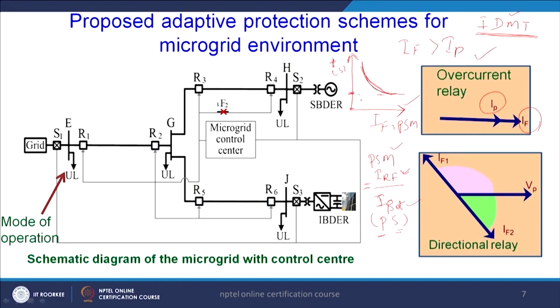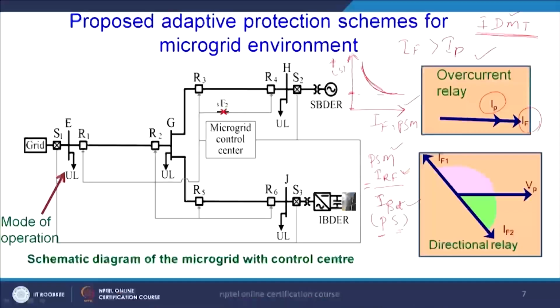We also have very inverse characteristics based overcurrent relaying principles, or extremely inverse type of overcurrent relaying principles, but in general in industry we prefer the IDMT type. After that, the time of operation is calculated and we maintain the TMS, the time multiplier setting, which sets the time of operation of the relay with respect to the time dial setting.